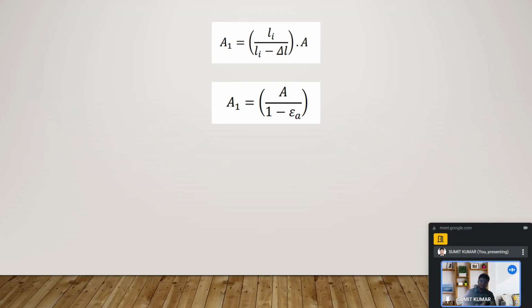Afterwards we get the stresses by dividing the value of load at which the failure takes place by this area, because during the test the change in length takes place, due to which strains get developed, that need to be compensated during our calculation. Otherwise our result will not reflect the true field conditions,